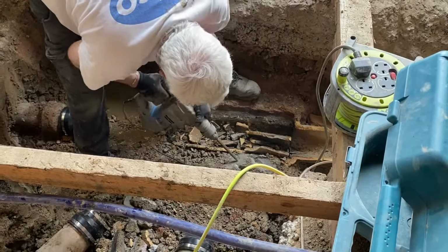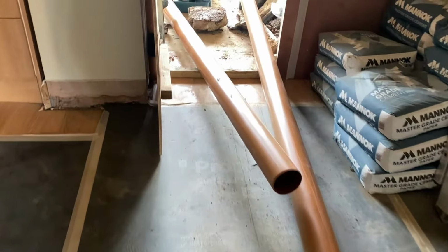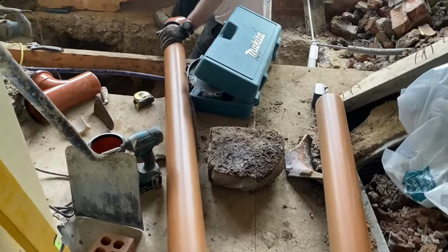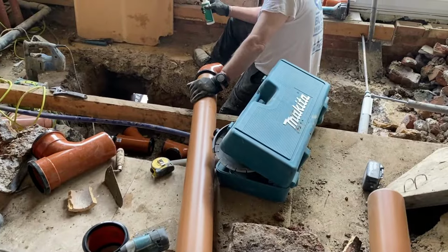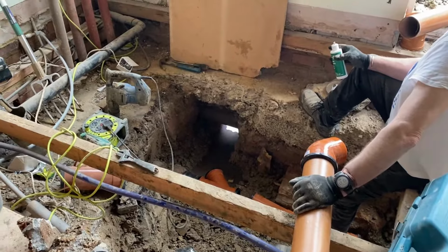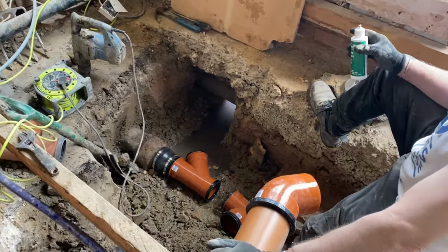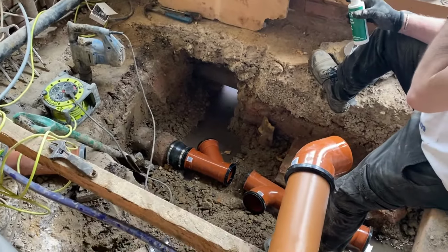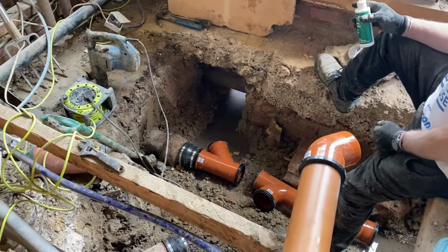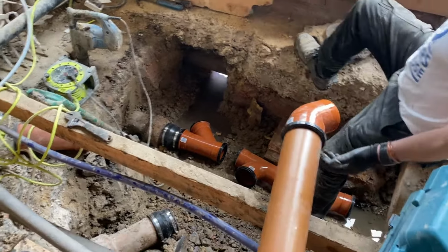So we're having to remove the old clay pipe here, and we're going to replace the clay pipe with new plastic pipework. The replacement of the old clay pipes with plastic is all compliant with building regulations. Nobody's using clay pipes anymore. It's a legacy from the past. So building control are happy for this section to be replaced with plastic pipe. But now it's really important to make sure that we get really good connections on all of this drainage, because this is all going to be buried underneath the extension. We're going out a further 3 meters. So this is going to be about 4 or 5 meters into the house.